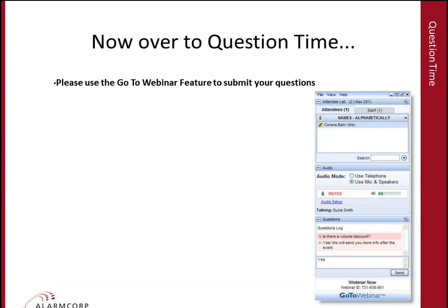However, we don't always need to go such a long distance, and as I said earlier, multi-mode solutions are typically cheaper. So if we don't need to go a very long distance, we can save often a significant amount of money by using multi-mode. Using single mode will not cause any problems, but it might be a case of overkill for what we need to do. But certainly, if the system budget allows for it, you can use single mode fiber all the time.